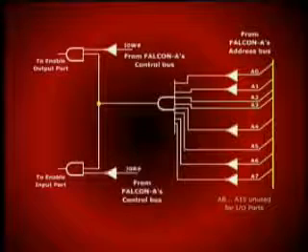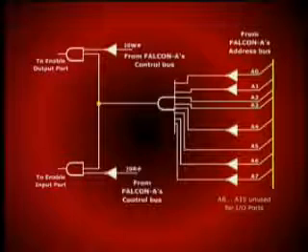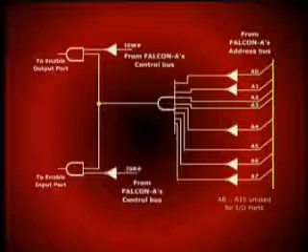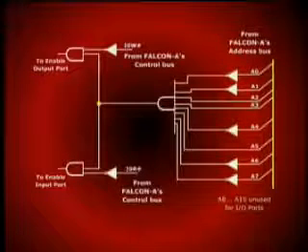For this particular example, where the address is 2C, you can easily verify after writing the binary pattern that the address lines A0, A1, A4, A6, and A7 would be inverted, whereas A2, A3, and A5 would be non-inverted.